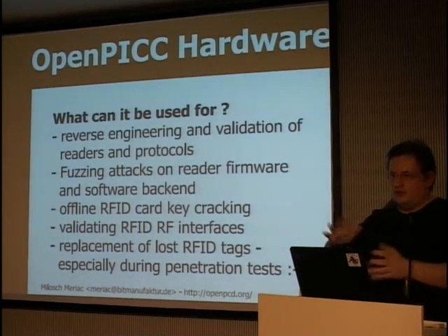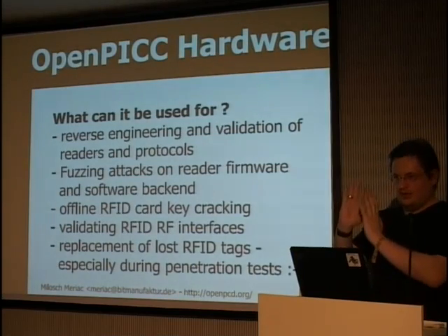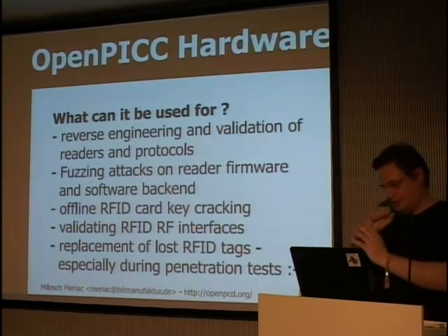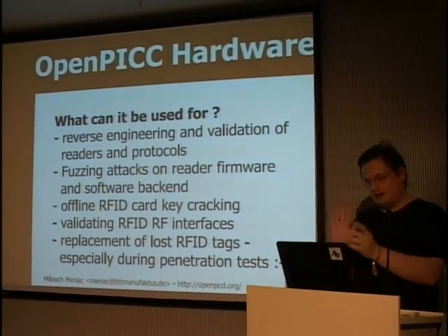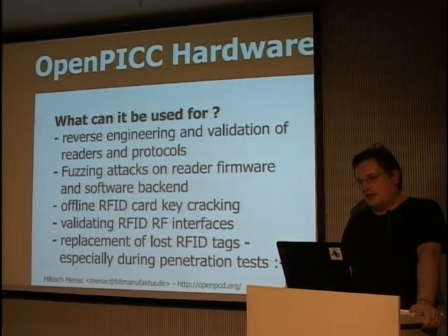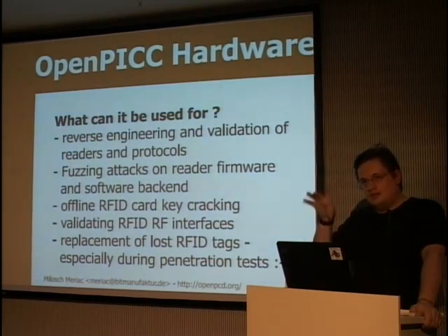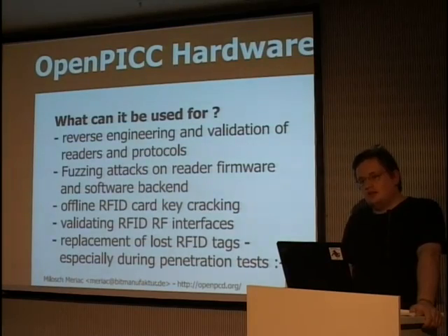The range is not very good, but you just put it between the reader and your real card, and you can easily get the decoded digital data over DMA. So you can reverse engineer simple cards very quickly, and you can even do a replay attack easily, because you have the possibility to send out data which is directly sent to the load resistors, which form the reverse path to the reader, and you can actually take the sample data and replay it.